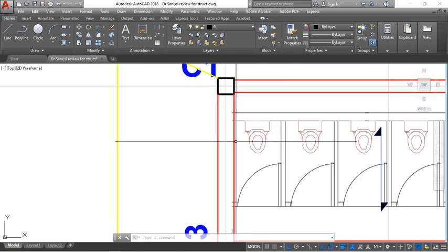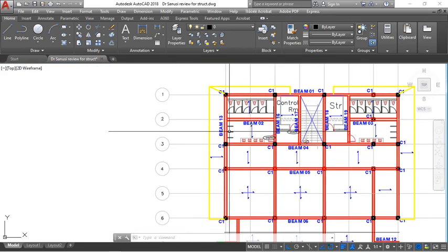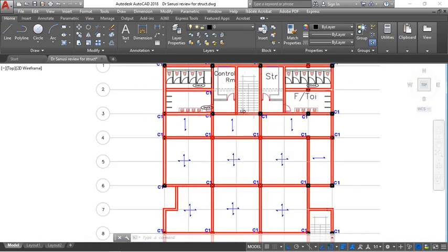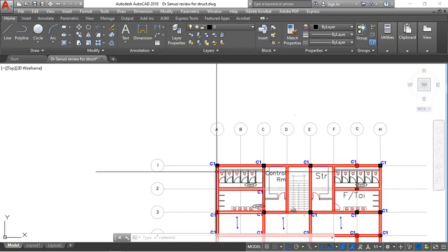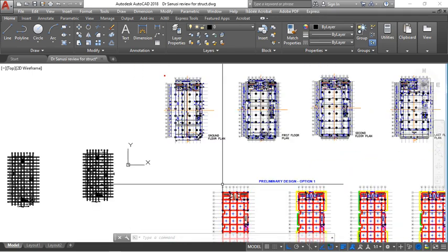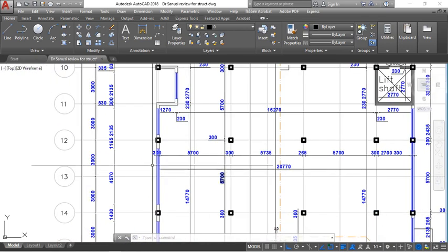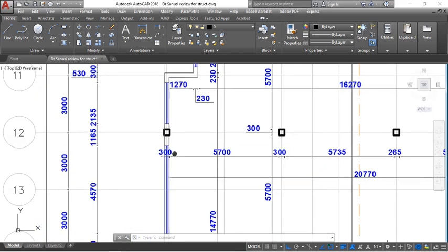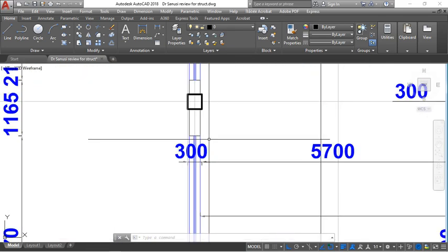After some time you start seeing cracks in the wall. So this also comes to: your wall needs a foundation, and the minimum recommended is 225. But it's sad that even professionals, engineers who are schooled, go and practice otherwise. They say it's just a wall.